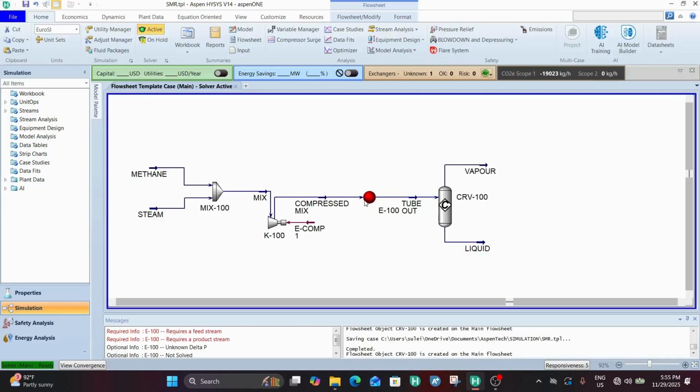But before that, our heat exchanger. So with respect to the optimization, what we have for temperature is 120.4 Celsius. We were supposed to plug this into a heat exchanger, basically recycling heat energy to avoid wastage. But unfortunately, it's going to be impossible because the temperature after the reaction comes out lower than the inlet stream.